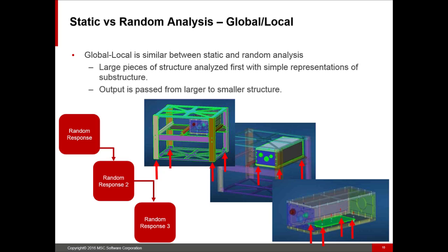He's going to get all that information summed up at however the thing is connected to the rest of the structure. So that's generally how this works out, and where we may not have to think about acoustics, we would use only Nastran to do something like that. But there could be other effects in there that could be driving it, again, reverberation off of the walls and the housing that we'd start to think about, where we would go, hey, I happen to have Actran, why don't I give that a shot and apply that to this internal structure as well.